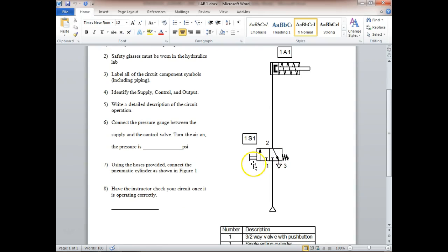So luckily, let's look at this valve and see what it is. So how many positions? 2. How's it operated? No, that's return. It's manually operated spring return. So when we talk about the operator, normally the operator is how the valve is shifted, right? So we can manually shift it both ways, or we can automatically shift it both ways, or we can automatically shift it one way, and then the spring would do what?